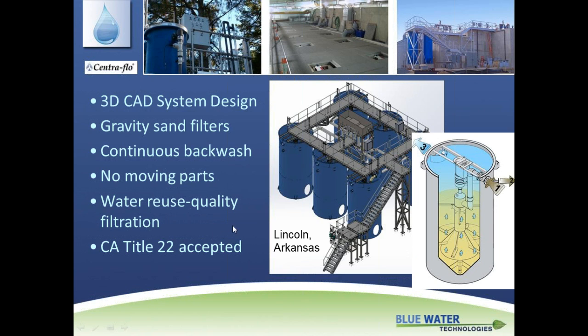But the nice thing about this entire system is, in addition to absorbing metals, it gives you filtration to reuse quality and reuse standards. In fact, these systems are California Title 22 approved, and they're approved for reuse throughout much of the U.S., throughout many states. It's a very simple design system. You have a couple of arrows in this 3D cutout here on the screen, so I'll just talk through the process. The water to be treated enters through where this arrow number 1 is entering the filter vessel.